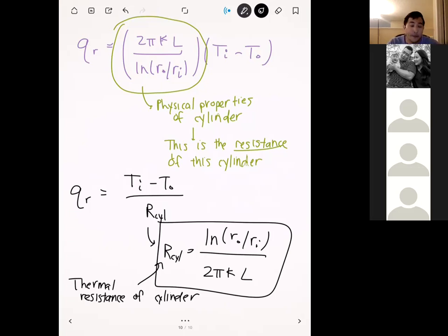What you don't want is, on a cold winter day, the water leaves the water heater but travels through so much piping that it loses all of its heat to the cold weather. So you want to design thermal insulation for these pipes so the hot water can reach the second floor without too much thermal loss.